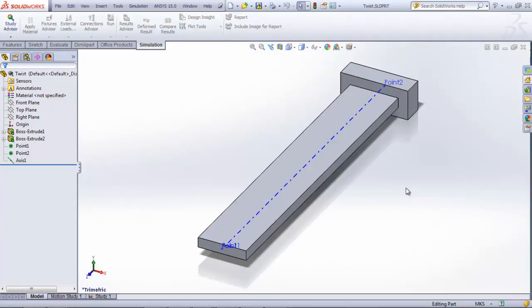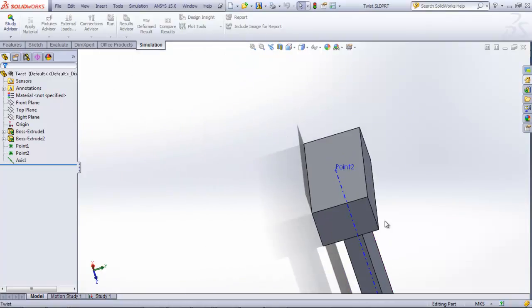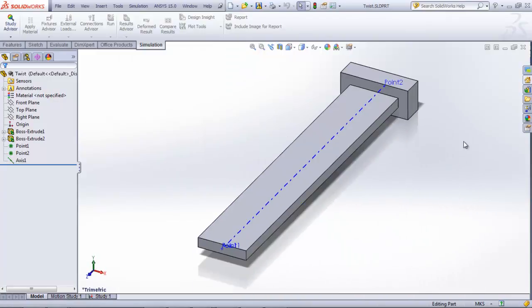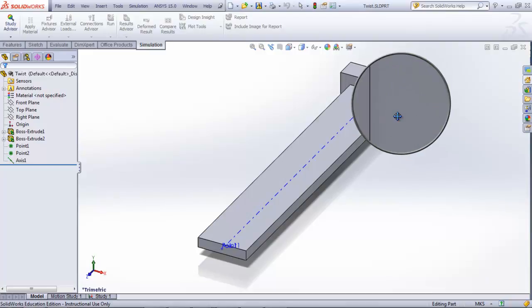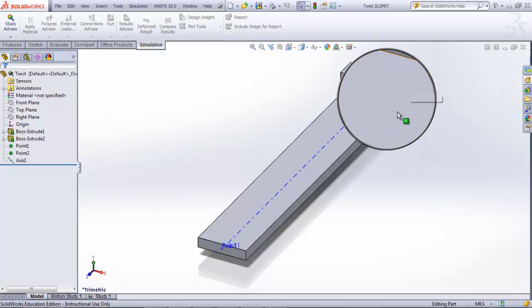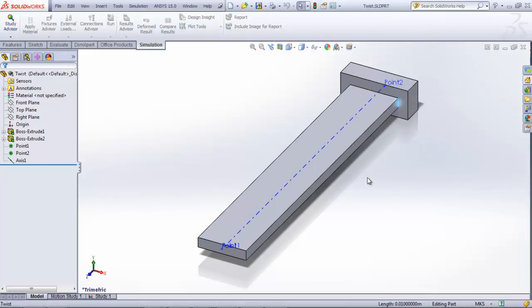The other one I use sometimes is when I'm trying to click really focused areas, and I don't want to keep zooming in and zooming out, moving back and forth. Just hit G. Move your cursor to where you want to see, and then press G. What you get is the magnifying glass, and you can magnify even more if you want to. You can hold down Control and middle click and pan to get into the right spot, so you can click, or even hit the sides of it, and that moves it well. I'm zoomed in pretty far, so it's really sensitive, but I can get right on that edge if I want to. Then it gives me the selection that I need. So that's a nice option there too.